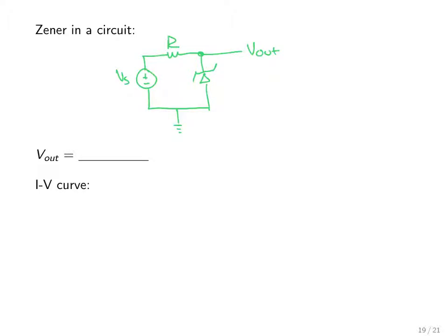The Zener diode would be upside down so that we're looking at its negative turn-on voltage. And it turns out it's quite linear with temperature. So V out here is approximately 10 millivolts per Kelvin, times the temperature in Kelvin. So that's pretty darn sensitive. And what you get here is about 2.98 volts at 25 degrees C, which is room temperature.